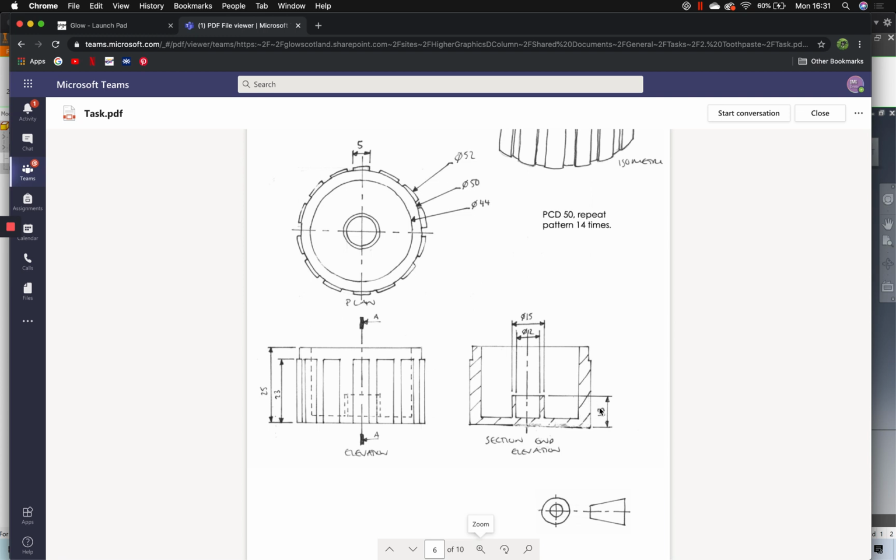We already know that the wall thickness is 3 millimetres, because we learnt that this line here to here is 3 millimetres, and from the base up is 13. But if we deduct the 3 millimetres of this wall thickness, we know that this line here would be 10.